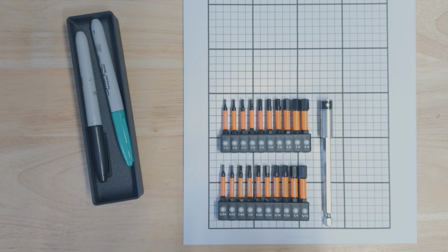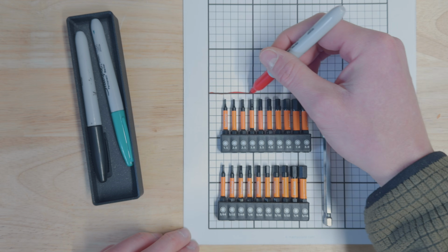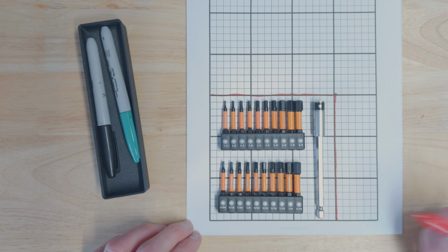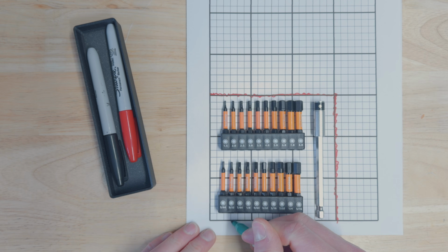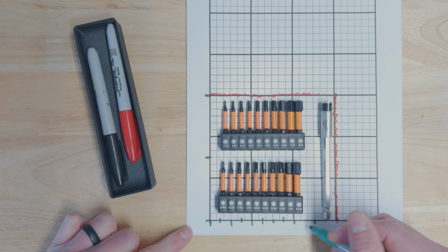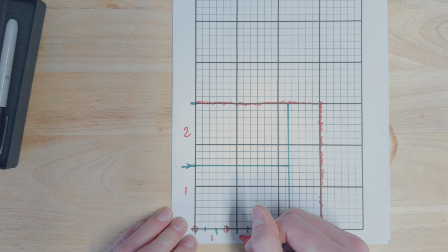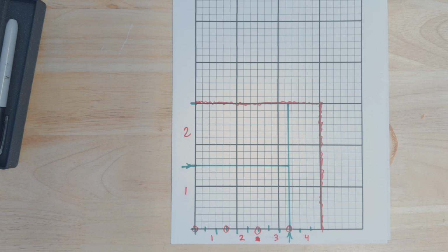To tackle this, I first outlined the overall grid sizing for the tools I have laid out, and I found that I'd need a 3x3 bin size to hold everything. Next, I started marking out halfway points that could help me approximate where I could start drawing evenly spaced intersections for everything, and kind of just repeating that halving process until I landed on a subgrid that would allow me that flexibility, which ended up being a 2x4 internal subgrid to properly set the tool slots.